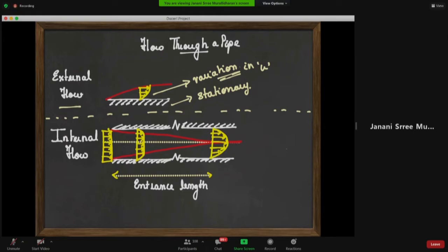If you have, say, flow through a pipe, which is what we're going to look at, typically at the inlet of the pipe, you have a uniform profile of velocity entering, right? Now, as you move along the tube, at the walls, you're going to have a no-slip boundary condition, which means that there is no velocity if your boundary is stationary.